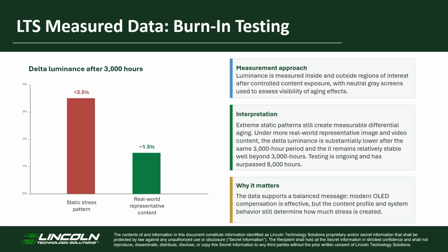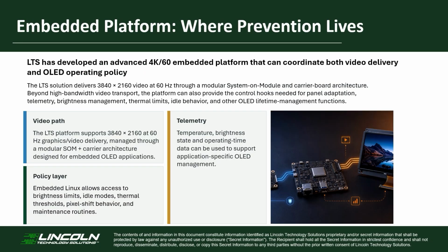LTS has developed an advanced embedded platform for 4K video at 60 Hz that can coordinate both video delivery and OLED operating policy. The platform uses a modular system-on-module and carrier board architecture to deliver 4K graphics and video at 60 Hz. The SOM provides reusable computing, memory, graphics, and operating system resources. The carrier board handles panel-facing interfaces, inputs, outputs, power sequencing, and application-specific integration.